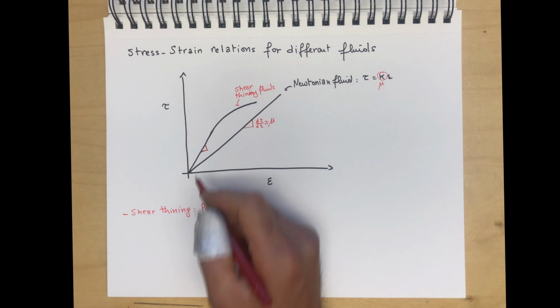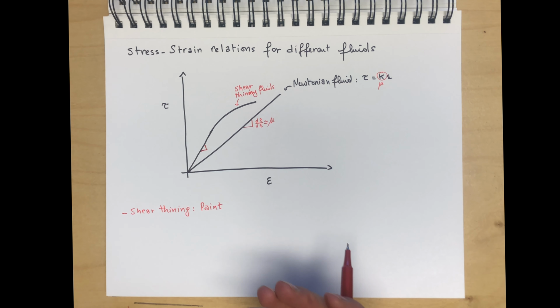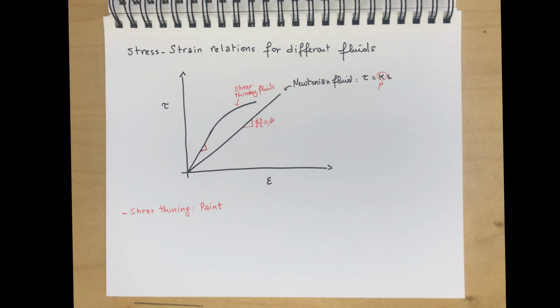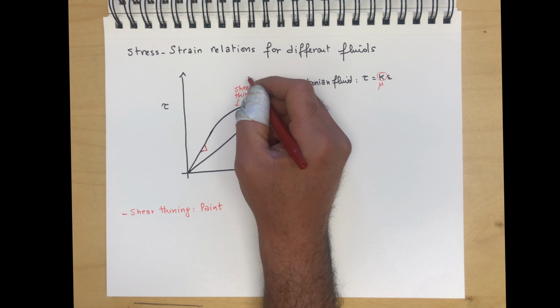That is going to reduce the viscosity essentially of the paint. It's going to thin it out. You're able to spread it. But then once you remove the stress, it's going to harden. And so that prevents dripping and all these bad things you don't want to have when you're doing paint. This is also called a pseudoplastic fluid.